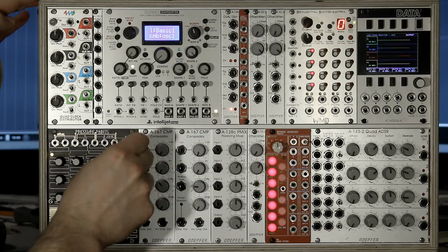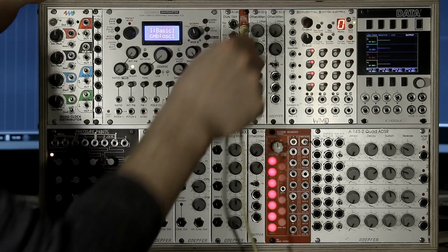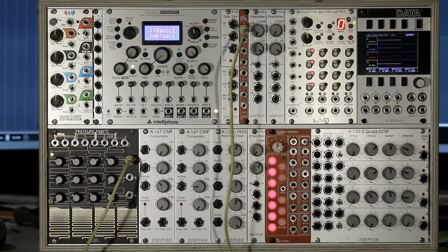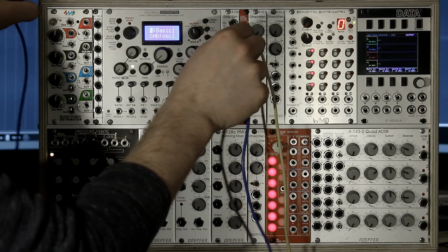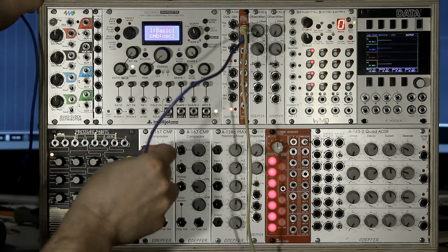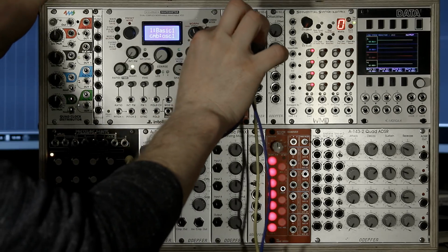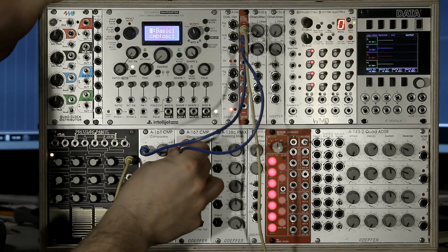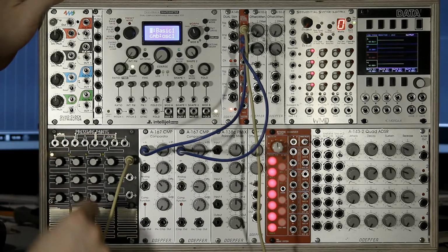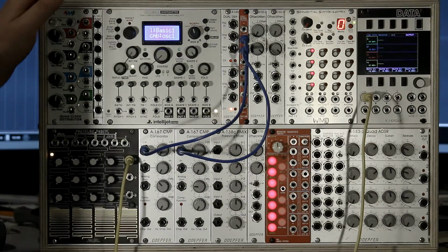Let's use Pressure Points as our main voltage source for now. Later it will be replaced with the LFO signal. We will need copies of the main voltage source, so I will use a buffered mult for better precision and connect the copies to both comparators. We will want to monitor this main voltage, so I'll run it through Data before anything.